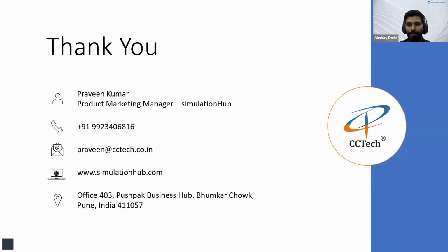The question is whether the software ensures that the Y plus falls within range to ensure accuracy, even if the results converge with low accuracy. Like I explained in the meshing part, there is a quality check that checks the quality of the mesh, and then it improves. Similarly, we have implemented a Y plus checker. Once the result is achieved, it checks the percentage of surface area or cells which satisfy the Y plus criteria based on the turbulence model.